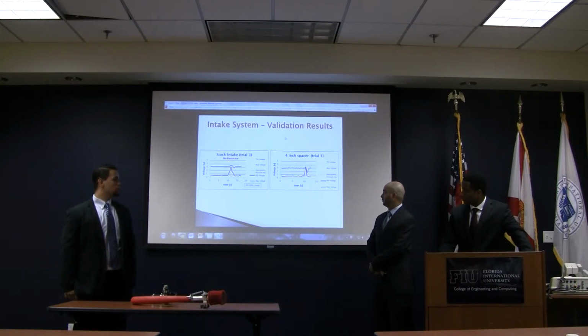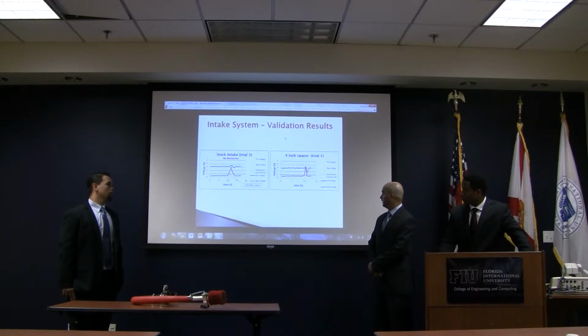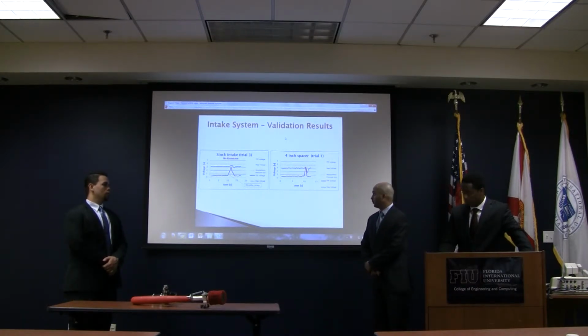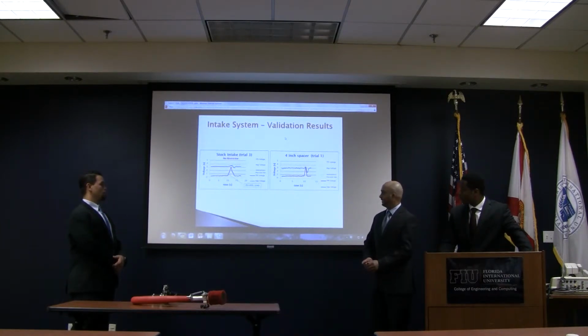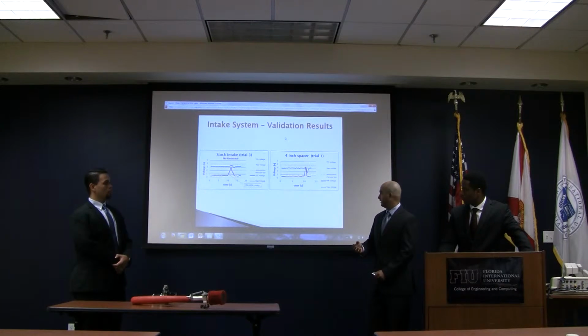What you'll notice is that with the non-restricted engine, the pressure voltage is much higher at idle than the restricted engine, and right at the spike you see an increase in pressure, then you see a pressure drop. That indicates that the engine RPM is still very high, and it's drawing a lot of air. As that throttle closes, that air is no longer available, so the pressure drops momentarily. Once the RPMs come down, then the system pressure recovers.